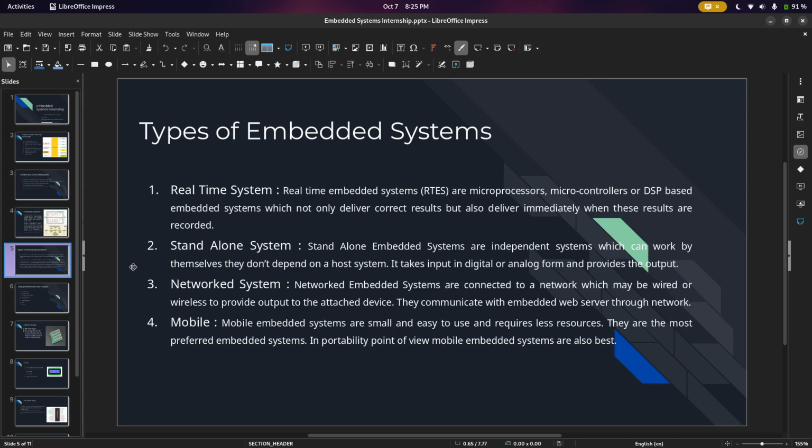A soft real-time embedded system can tolerate a deadline that has been given to it, but the other type of embedded system which comes under the real-time system cannot avoid the deadline that it has been given. If the deadline is avoided in a hard real-time embedded system, it can cause harm to a human life, or it can cause heavy damage to capital, or can result in loss of money. Examples are the military usage in defense sector or medical usage in the health sector.